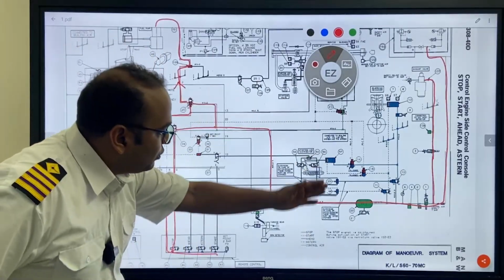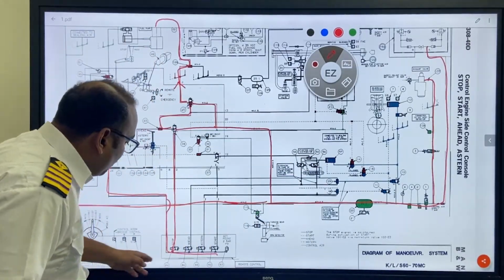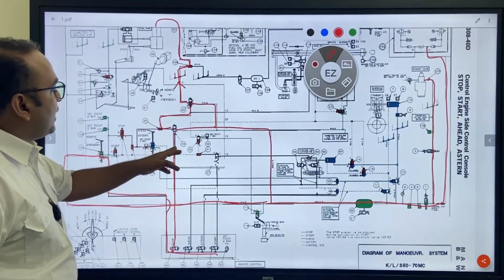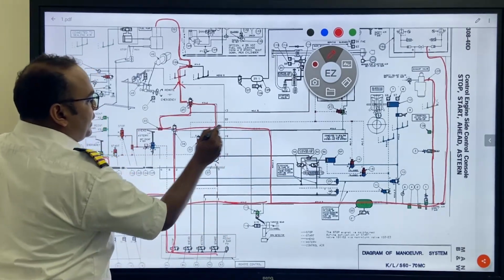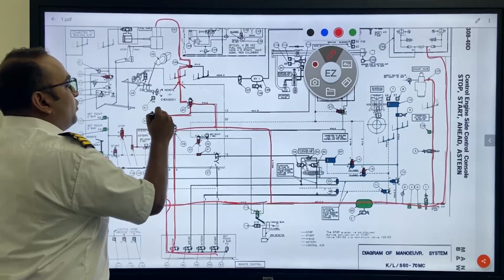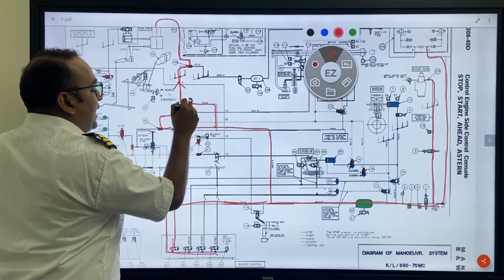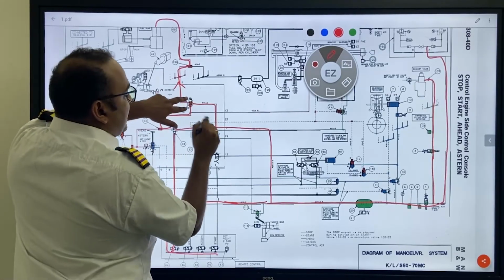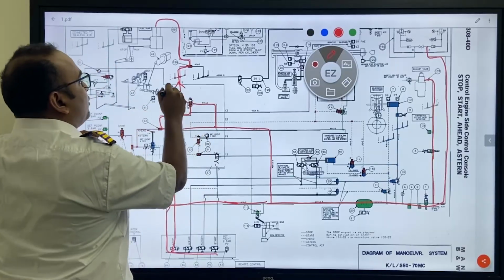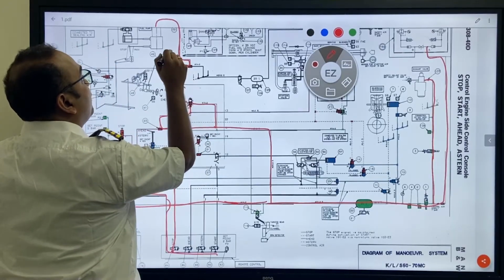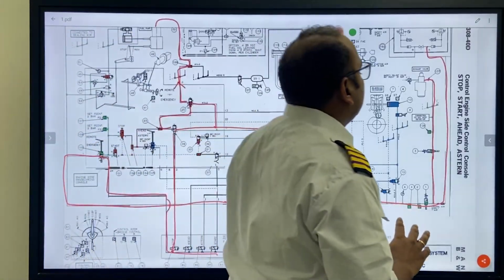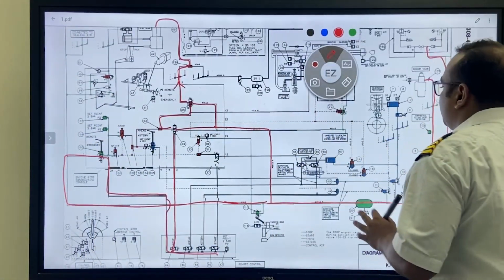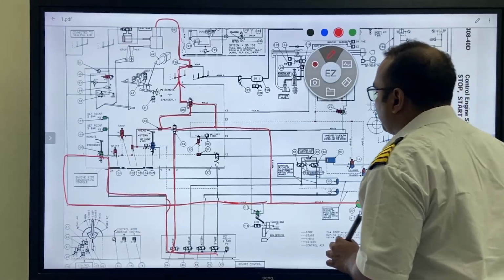So this is what is happening. One control air came via this solenoid valve, via 38. One section of the control air crossed 38, went over and activated 25. The same section of the control air went over via double non-return valve 128 and has actuated the puncture valve. So this is in the stop condition and it is in the initial condition. This is what is happening.